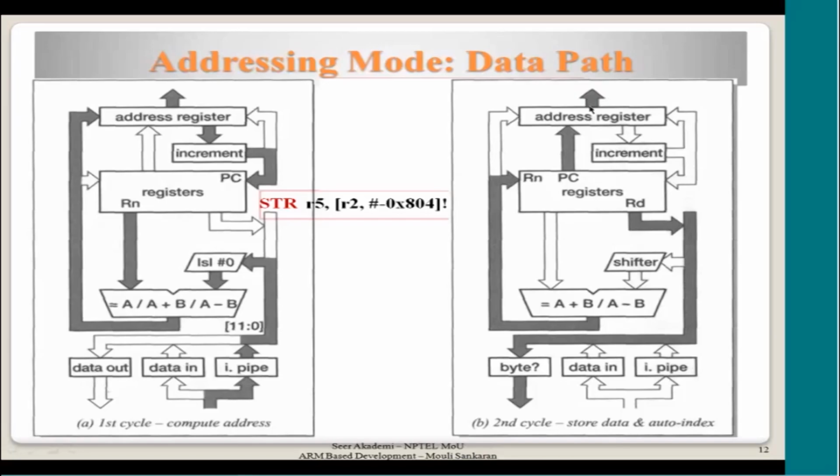Okay. So the next instruction address is going out from the PC. That is why it was saved earlier and then now taken out from this. Please remember, whatever value is there in the address register is overwritten by the address calculated by this. The previous PC value would have been gone, so that has to be kept in the PC. That is why it is done this way. Okay, I hope this is very clear to you.